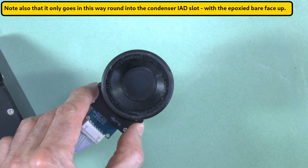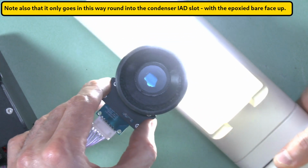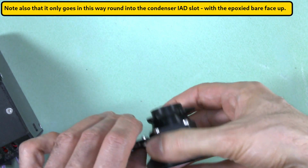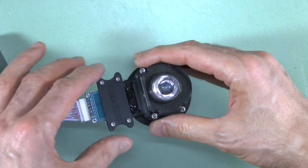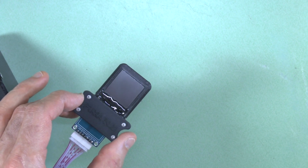Never force it in. When removing the SLM from a slot, I usually push the SLM from behind as shown, rather than pulling it out via its handle, because pushing it out in this way results in less chance of accidentally putting bending pressure on the thin glass connector plate.